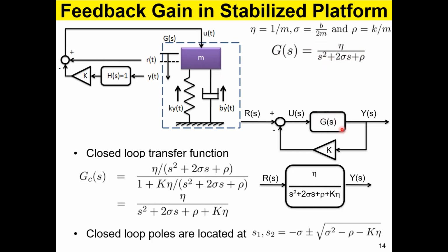If you have an open loop transfer function like this shock absorber, and you generate a feedback through a gain, through a summing point here, you get the difference as a control signal to drive the force onto the mass. So we design this loop, signal connectivity, gain, etc., to make it a feedback closed loop plant.